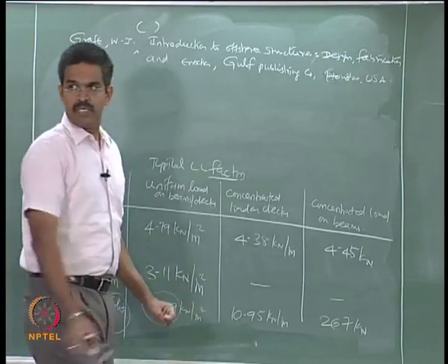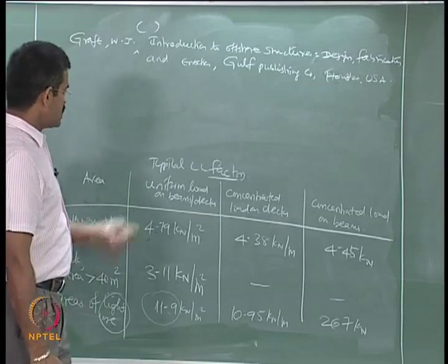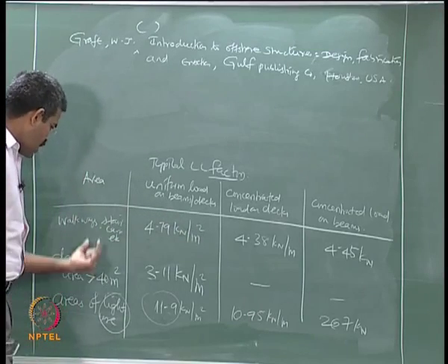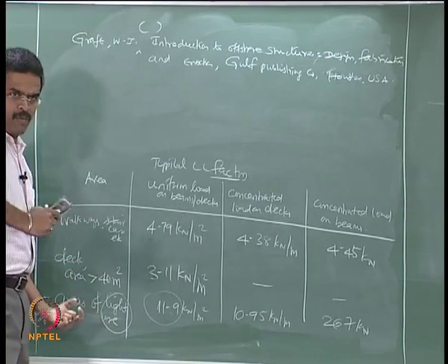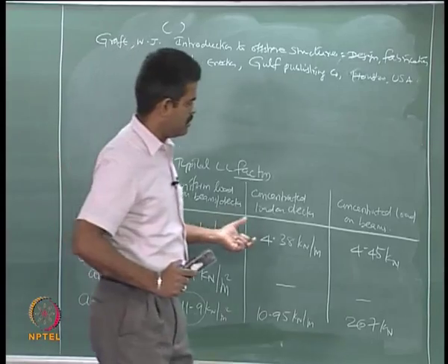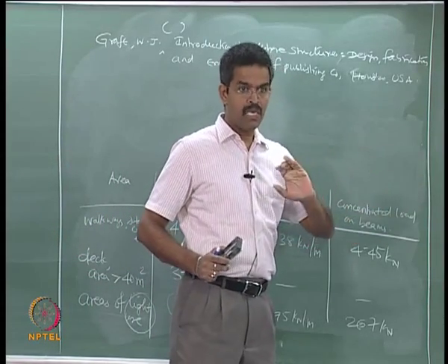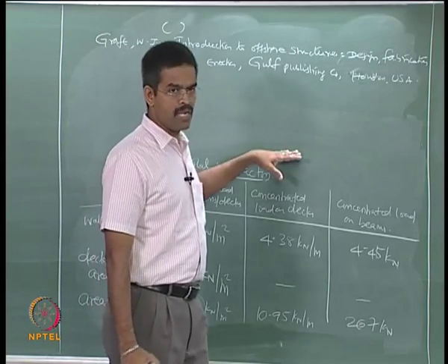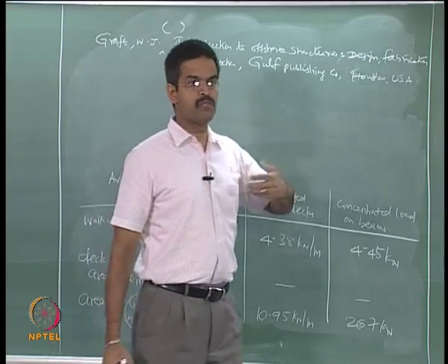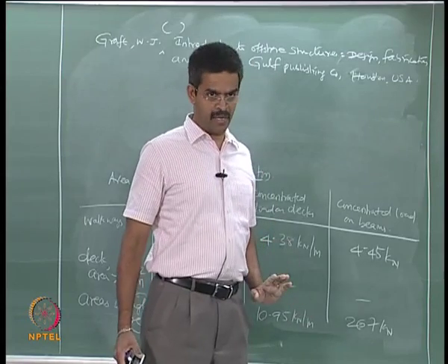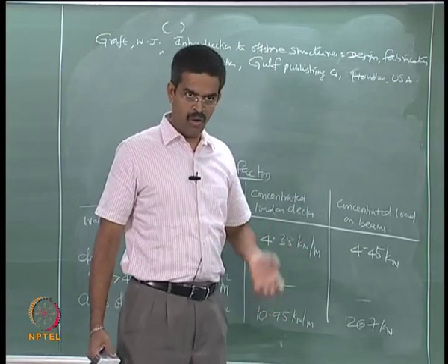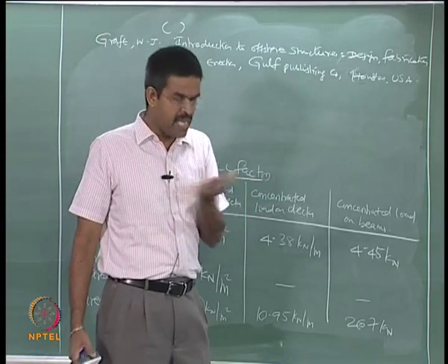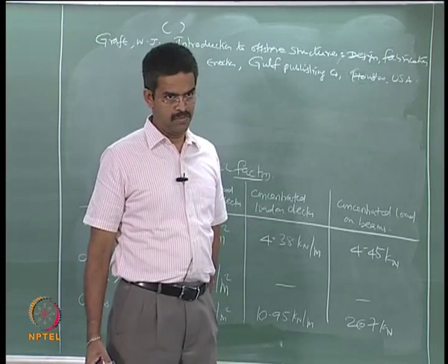Now interesting factor, these live loads are considered static, but they essentially come from movement of equipments or vehicles or drilling derricks, etc. So there should be some impact on this. Why will impact be there? Because when any vehicle or any equipment operates or moves and applies a brake or changes its speed or alters its acceleration and velocity, it will cause an additional impact to the restraint offered by the support.